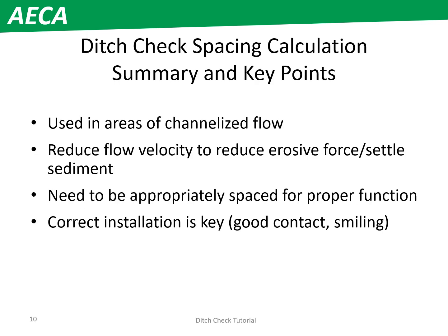So to summarize the key points from today's video, ditch checks are used in areas of channelized flows, like roadway ditches and drainage swales, to reduce flow velocity and in turn erosive forces, as well as promoting sediment dropout from the runoff. Ditch checks need to be spaced appropriately to function. If they are too far apart, you won't achieve the runoff velocity reduction benefits. And finally, correct installation of ditch checks in the field is key to having them function properly. You want good contact with the ground, and don't forget to make them smile.